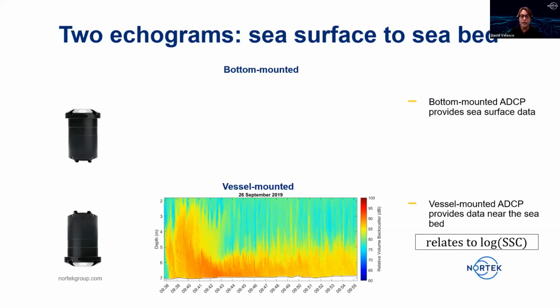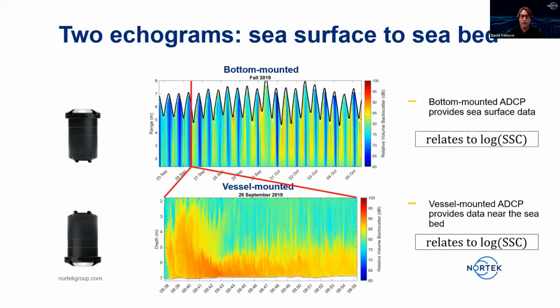And now here's the data from the up-looking system. This is taken from our OceanContour software. Here, of course, we miss the near-bed data due to the physical installation height of the instrument, but we do get data very, very close to the surface itself. And the same corrections have been done that allow us to compare these two instruments. From here, we can start making some more accurate inferences about what's actually going on with the sediments themselves.